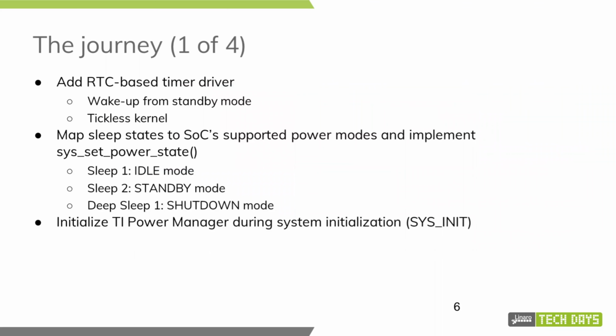And now I'll just walk you a little bit through my journey. So I first added a timer driver that is based on the RTC, because it has the ability to wake up the device from standby mode, as opposed to the standard SysTick timer that's on the M4, which doesn't have that capability. And as part of that, I made sure that it supports the tickless kernel mode, so that we can leverage that. And then I map the sleep states to the supported power modes on the device.